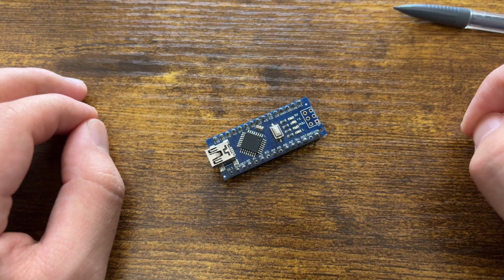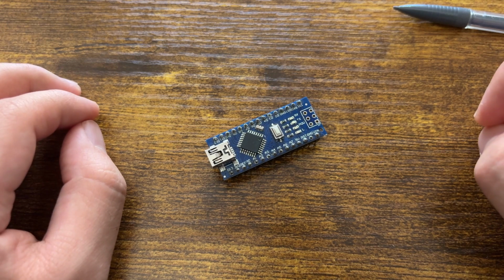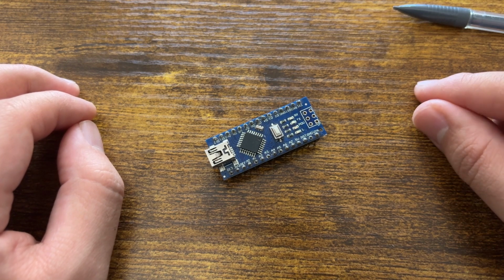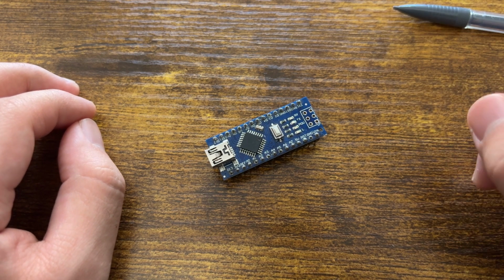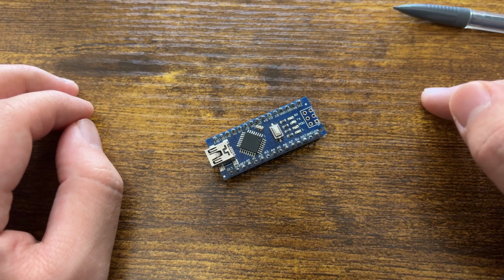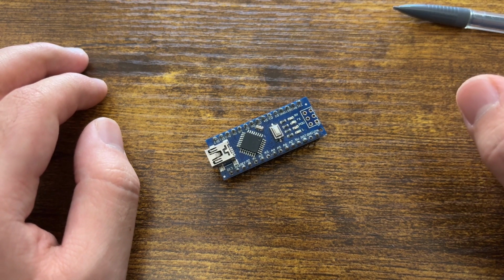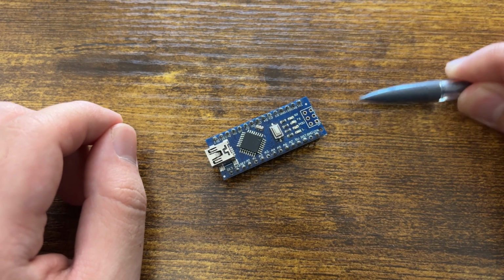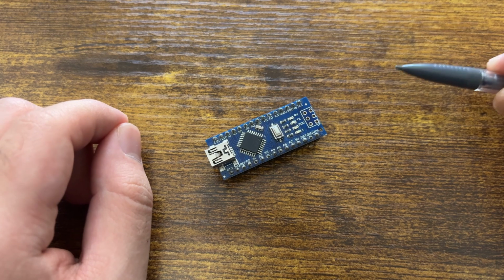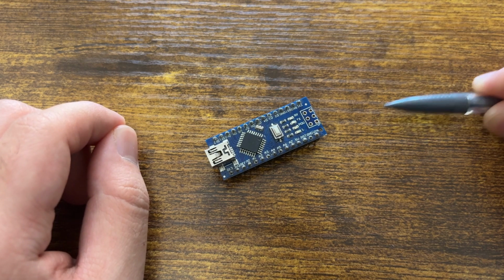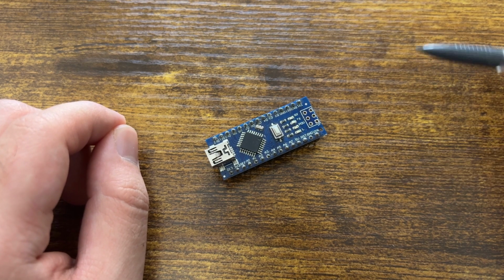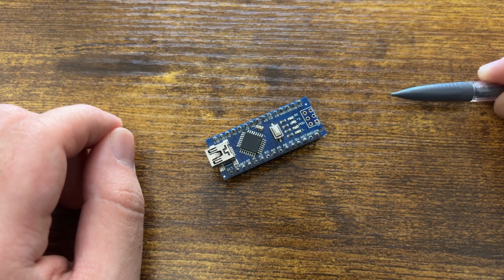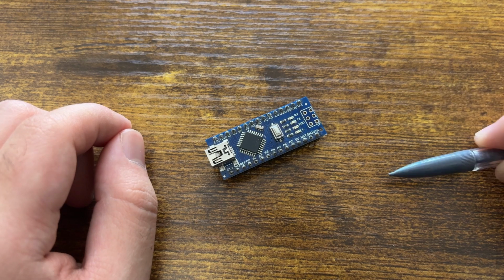So we need to translate this and tell the microcontroller that we will use, let's say, 5 volts as a high pulse and 0 volts as a low pulse, or logical 1 and logical 0. Also, we want to tell our microcontroller how wide this pulse will be. So for example, we want to send 2 pulses of 1. So we will send, for example, 0, 1, 1, 0. And what we need is 0 volts, 5 volts, again 5 volts, which means we will stay on this level, and then 0 volts again.